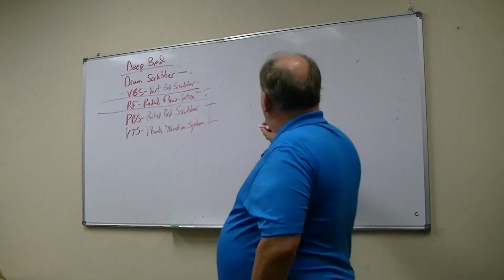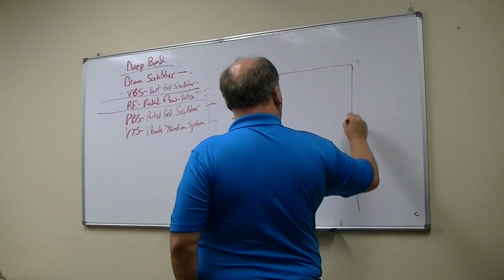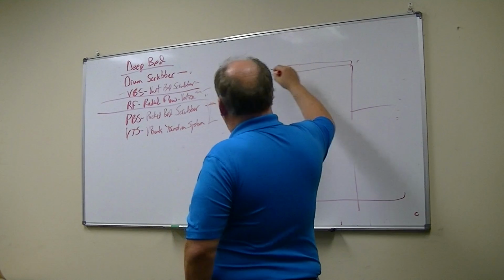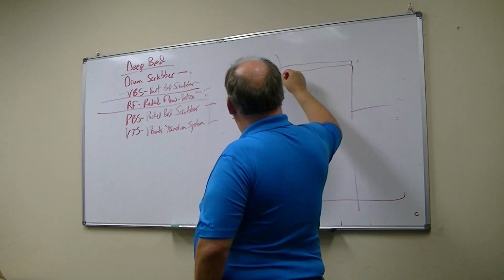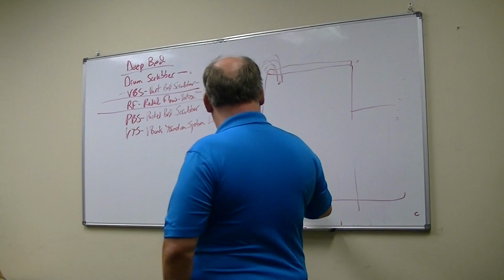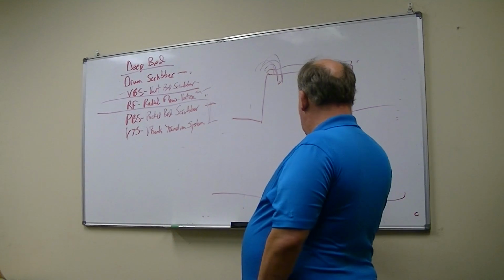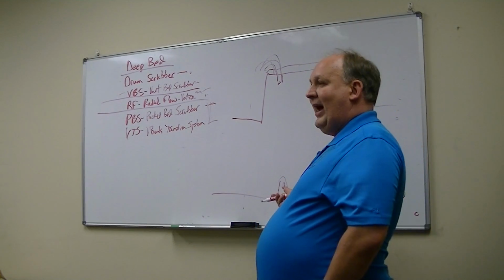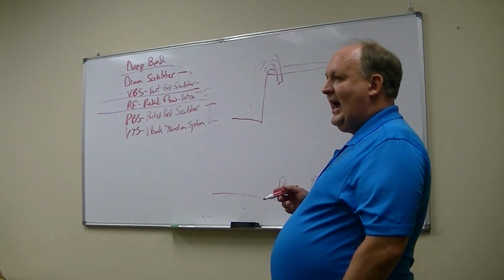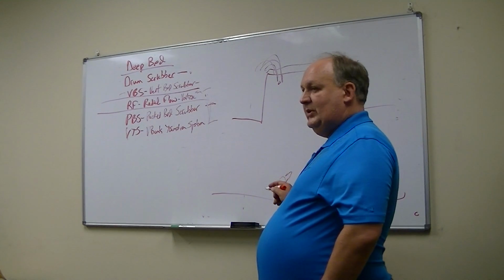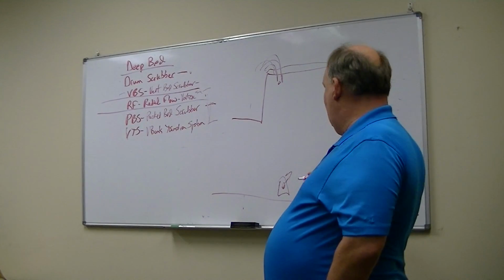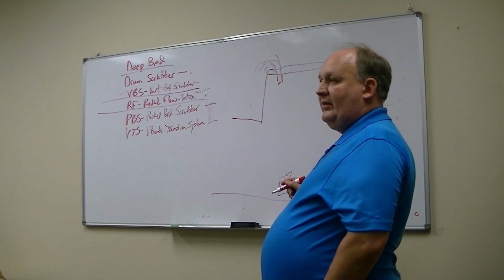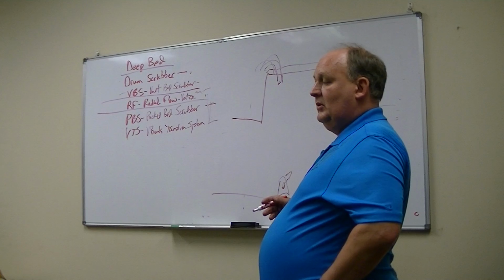So, yeah, in a PBS unit, we've got the Fill-Chute on top. Most customers will come in with a big vacuum hose and just vacuum out the media. But we do put on the side these Fill-Chutes for them to be able to hook up a vacuum truck and pull that out. The reality is, guys, nobody's using those vacuum attachments. We're probably wasting a lot of money on that. We could probably just put a flange port on there and not worry about the vacuum port, unless the spec calls for vacuum ports with it.